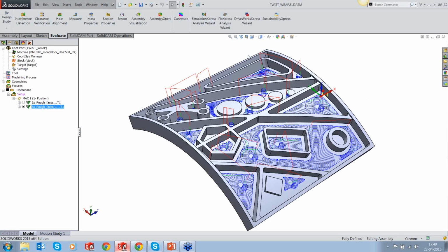You can also use multi-axis roughing for finishing the floor, because it gives you one single homogeneous toolpath. So there are a lot of uses for multi-axis roughing, but the most important one is to rough out material from pockets in full 5-axis. Right.